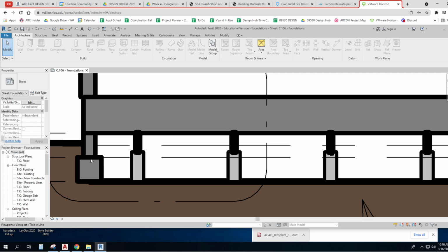So it's not waterproof. And most places will ask you to put what they call a vapor barrier around your concrete, underneath and up the side, to put one more barrier against water intrusion. So those are some of the things we always want to see. How does it do with pests, with water, and fire?